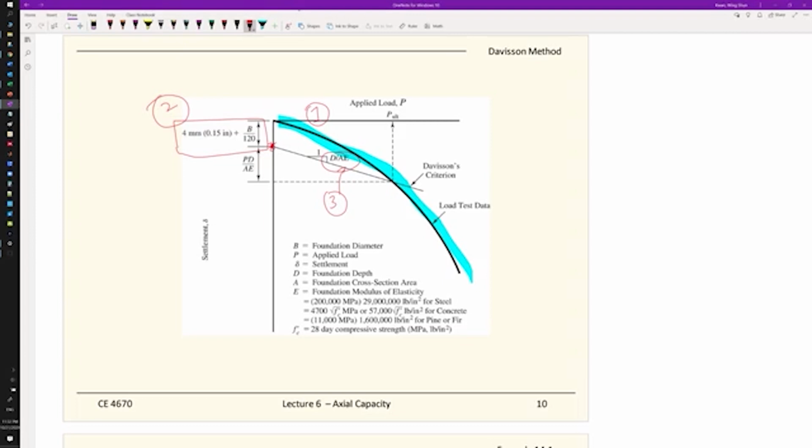But in many cases, you may have a drilled shaft, and for a drilled shaft, that is concrete with steel reinforcement. I hope you have taken your concrete design class at the 4000 level, so we learn about all this good thing. So you have steel reinforcement plus the concrete. So those are the drilled shaft. When you calculate the modulus for the composite of steel and concrete, you need a formula. We talk about that. So the f'c again is the compressive strength at 28 days. For your material class, you should heavily cover that.